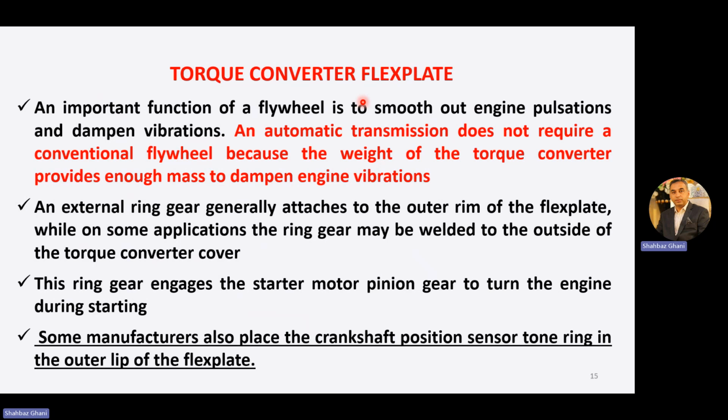Now, torque converter flex plate, a few more words about it. An important function of a flywheel is to smooth out engine pulsation and dampen vibration in a manual transmission vehicle. An automatic transmission does not require a conventional flywheel because the weight of the torque converter provides enough mass to dampen engine vibration.